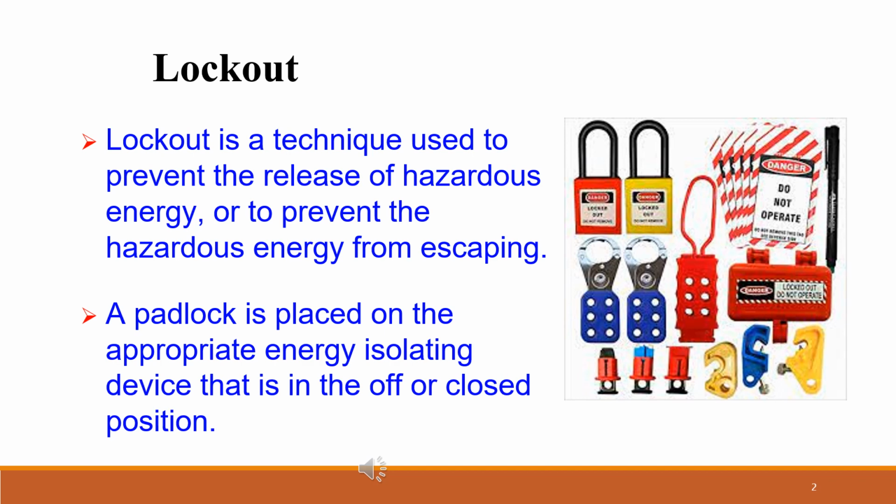Lockout is a technique used to prevent the release of hazardous energy, or to prevent the hazardous energy from escaping. A padlock is placed on the appropriate energy isolating device that is in the off or closed position. We will discuss more about LOTO in the next parts.